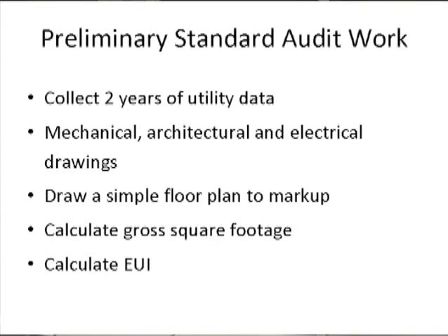I'm going to use one of them for lighting, I'm going to use one of them for HVAC, and the HVAC is not going to all fit on there. I'm just going to note things as I go through the building. I'm going to look for inconsistencies in the building, how equipment's running, how equipment's being maintained, and I want to make notes of that. And maybe oversized equipment and things like that, or spaces have changed.